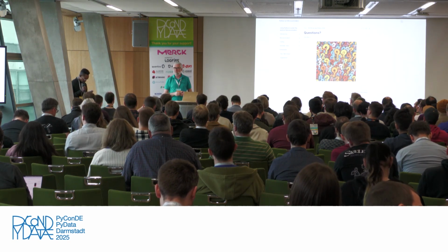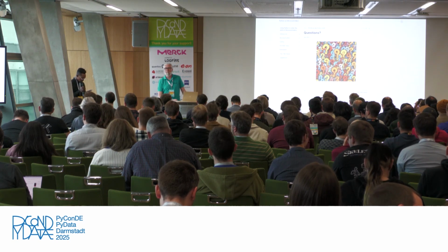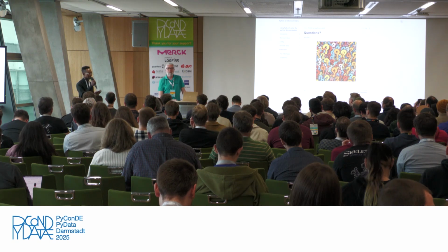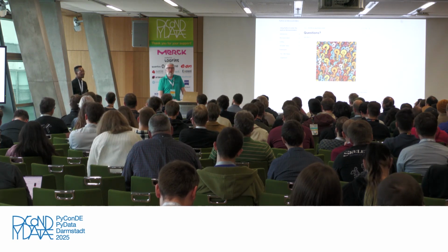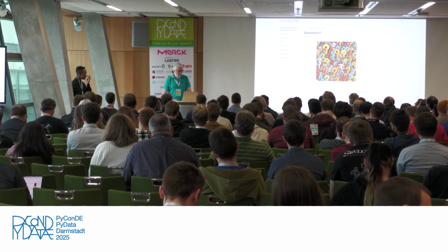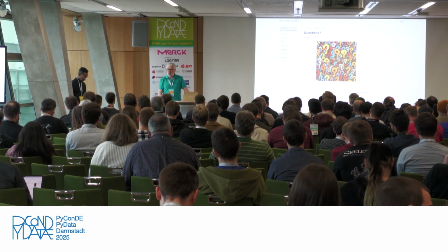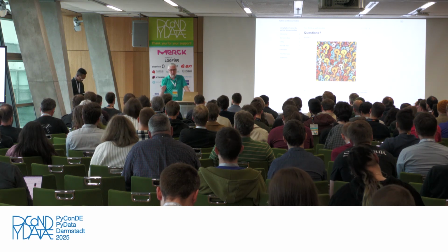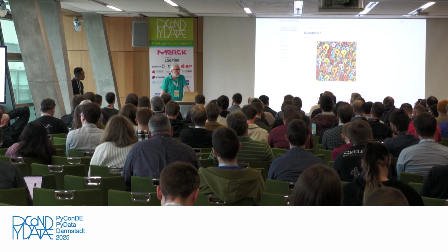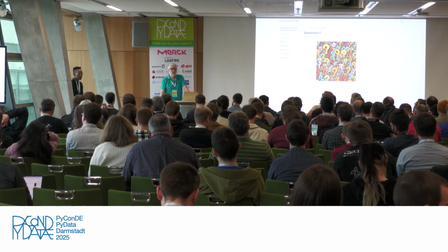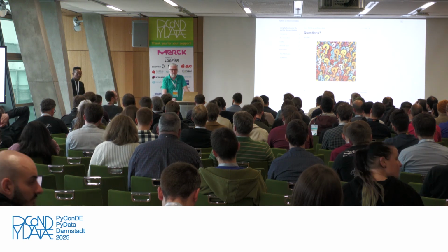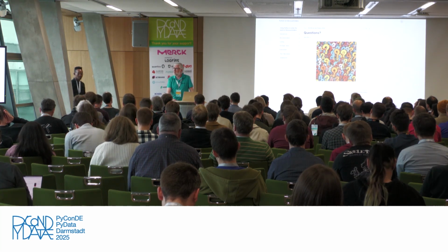Good. Another question: is there an alternative to Wi-Fi? I can't connect to anything in my basement, and someone is concerned. When it comes to long range in-house, it can be difficult not to use Wi-Fi. So the usual suspect is Bluetooth. That won't help you really for long distances. Another alternative is LoRa. That will work in-house probably, and also out of the house with not a lot of data to be transferred. Those are options. Else, repeaters, I guess.